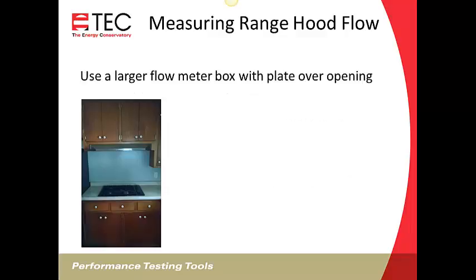Now we're going to go over a review of those 3 methods we talked about for measuring range hood flow. The first one was using a larger flow meter box with a plate over the opening. That flow meter box we talked about was 1.5 times the exhaust fan flow meter box. We're going to cover over the opening of the range hood and attach that box to take a measurement.